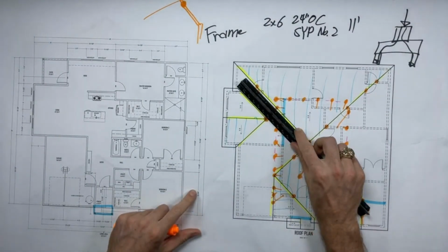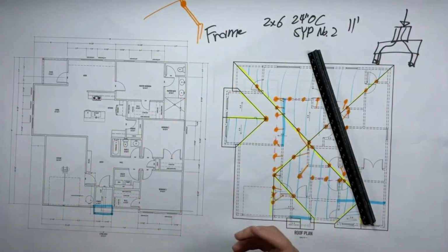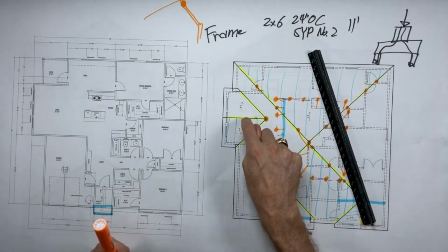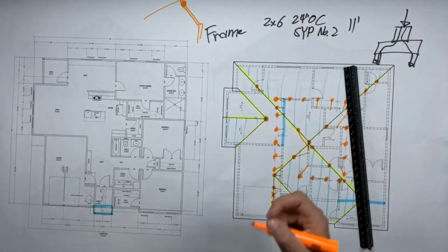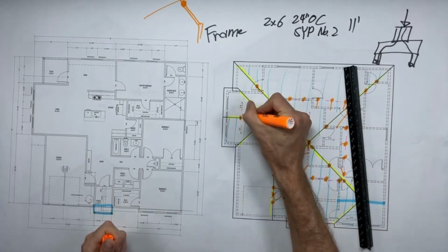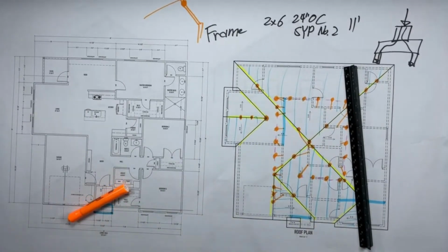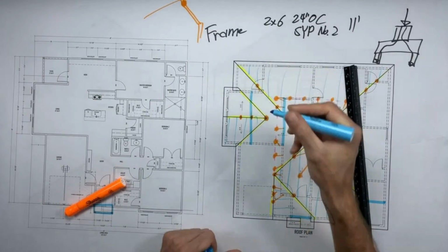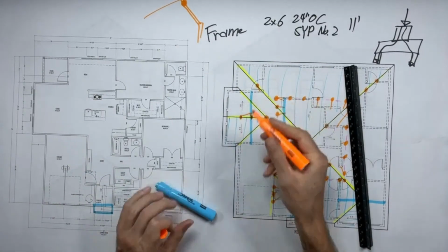How far is this? 10 feet? 10 feet from wall to ridge. So I should probably put a support in here. And I need to support the ridge in the middle of this anyway. I need at least one support in there. So what I'm going to do is probably put two in, and then I need support for my hips anyway. So I'm just going to run another beam right through here. And one of these braces can go down on the beam like that.